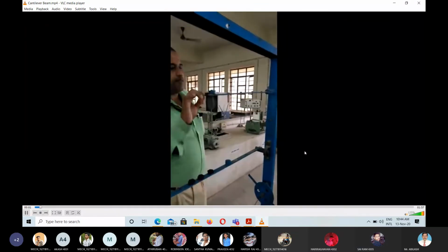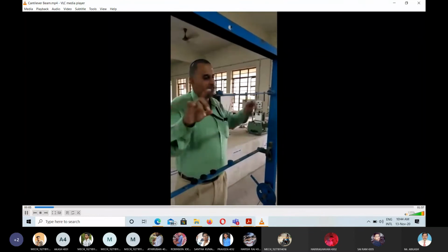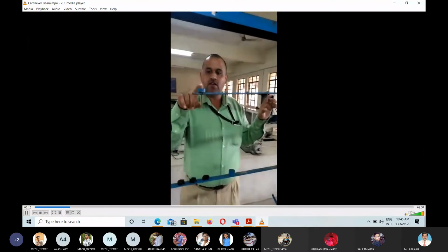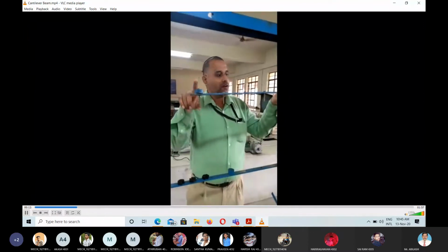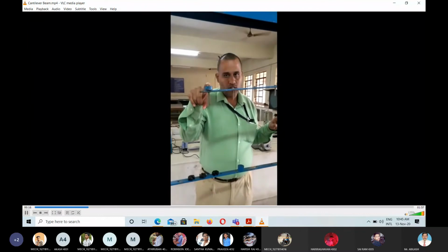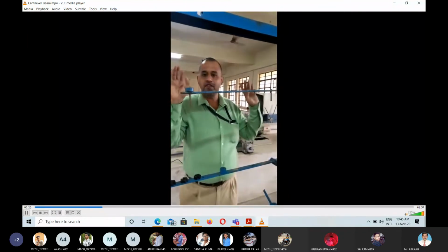Guys, this next experiment is transverse vibration on cantilever beam. This is your experiment. We are going to take two types of readings. One is loaded at the end. So you are going to load it at the end and add the incremental load. You are finding out the vibration frequency of the system.